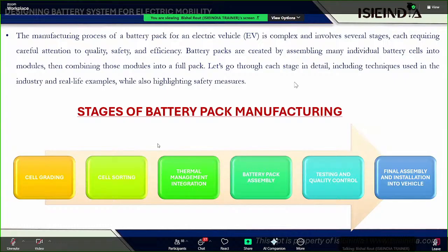What do blade battery architectures look like? A blade battery consists of an LFP chemistry, but the design of the blade battery is such that the heat is dissipated on the surface. Although LFP is good for heat dissipation and heat accumulation, the design of an LFP blade battery is just like a blade structure. It is vertically long, not a horizontal structure. So it is a blade-like position. That's why we call it a blade battery, right?